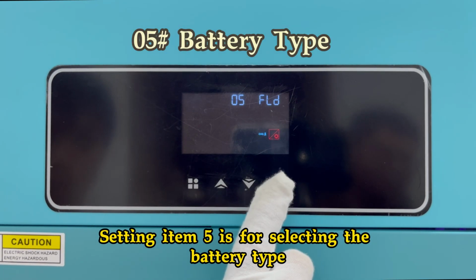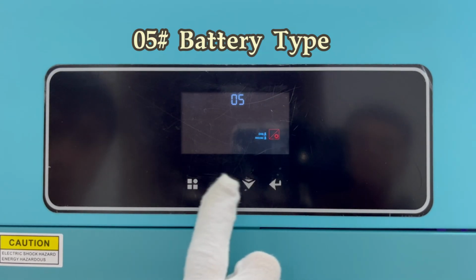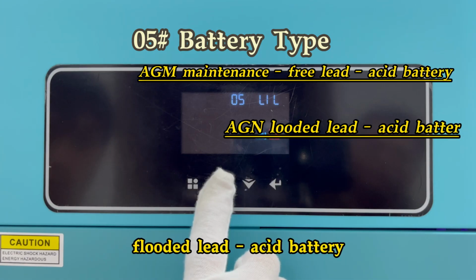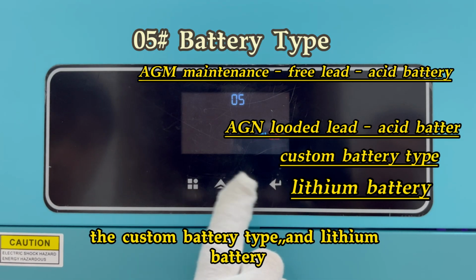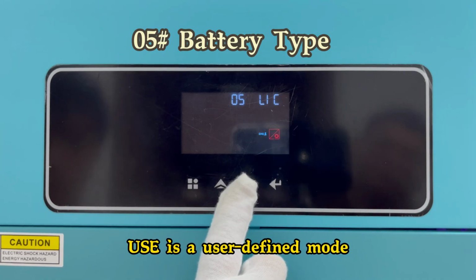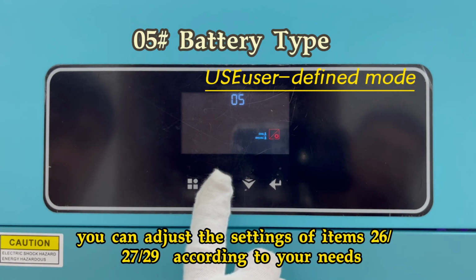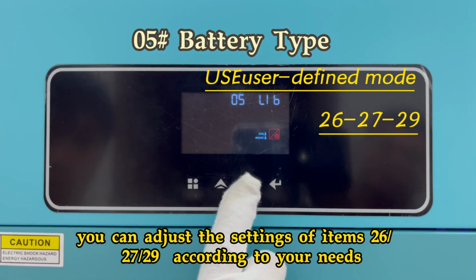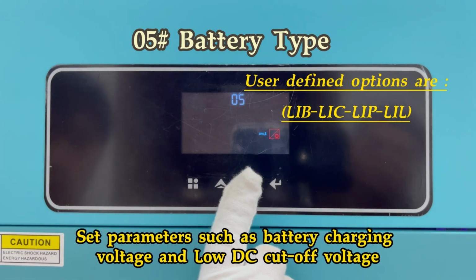Setting item 5 is for selecting the battery type. The available options are maintenance-free lead-acid battery, flooded lead-acid battery, the custom battery type, and lithium battery. USC is a user-defined mode. If you choose the custom battery type, you can adjust the settings of items 26, 27, and 29 according to your needs. Set parameters such as battery charging voltage and low DC cutoff voltage.